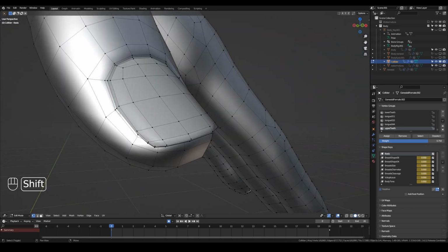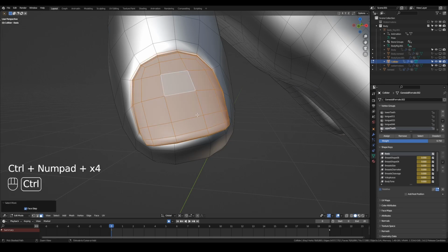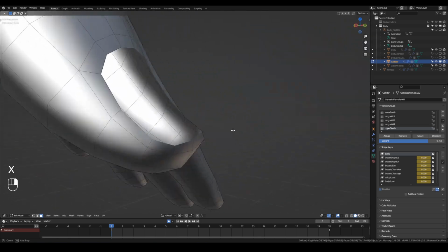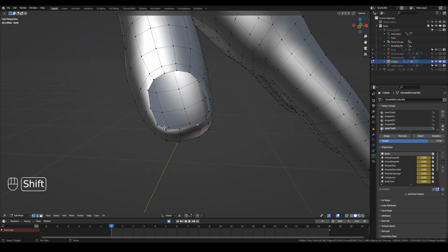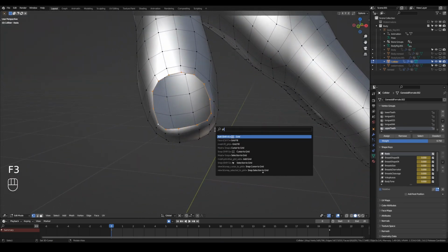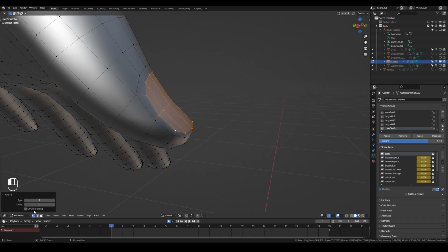You can select faces one by one, or just, like me, select some in the middle and expand the selection by pressing Shift and plus on the numpad. Then, as previously, select the hole and grid fill it. Sometimes clicking simple bending gives a smoother result.